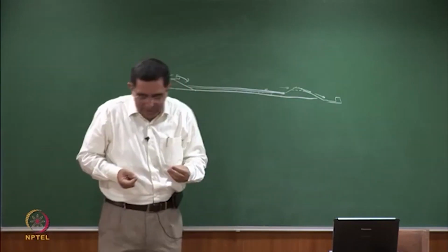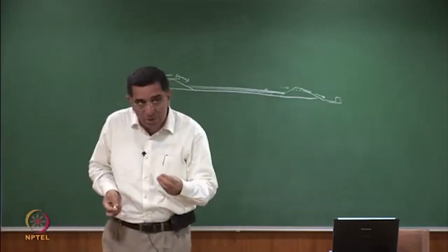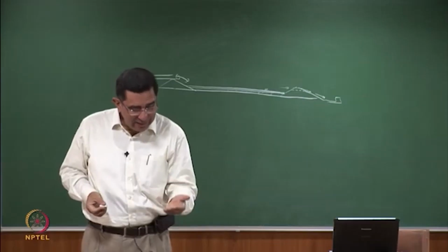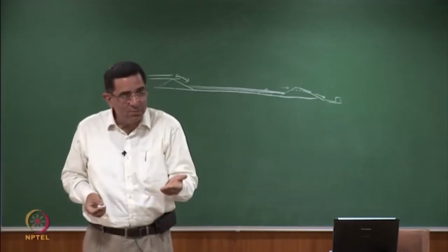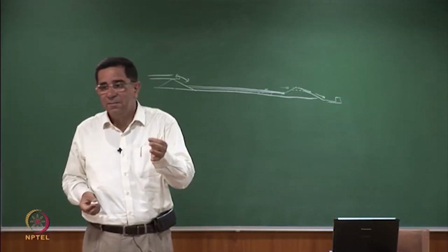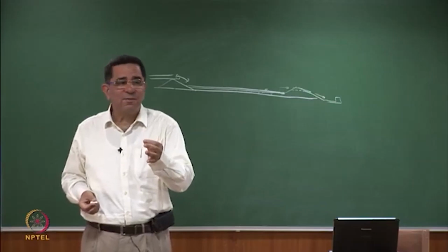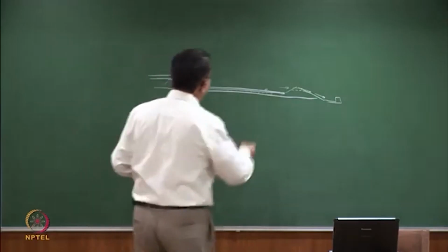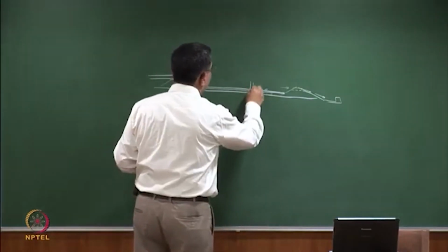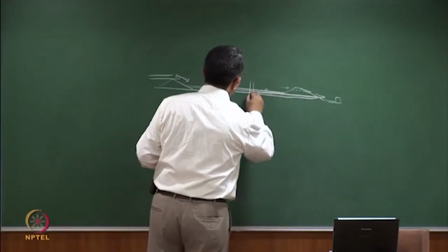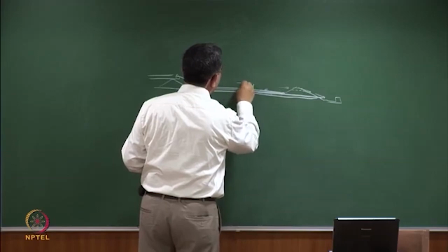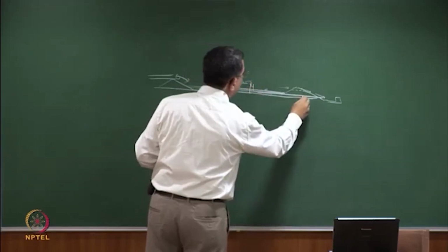So I need a decanting arrangement which allows the water to come out as the ash settles and the clear water moves up. That's the criticality of design. Otherwise, I can always make a well, right? So just like you have the overflow weir, I can make a well that when the water is at this level, it will flow into this and go out.